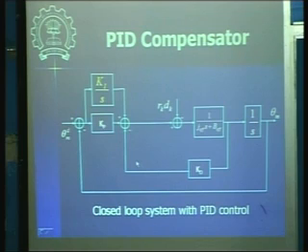This is how the PID controller will look in block diagram fashion. The entire thing is the same as the previous block diagram for PD control, and now you have added one more term in your control expression corresponding to the integral control action. This is how your PID controller will look, and the disturbance is still entering your robot equations.